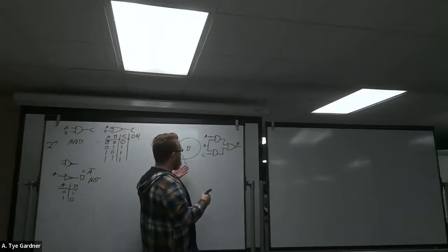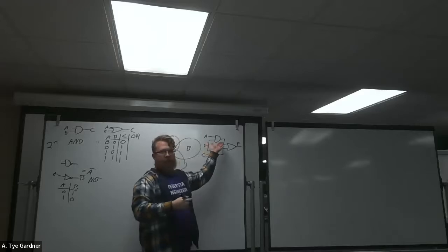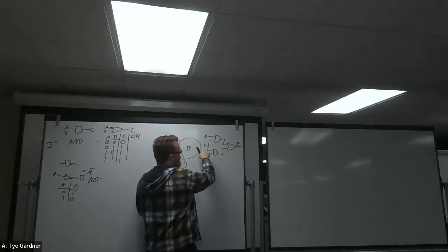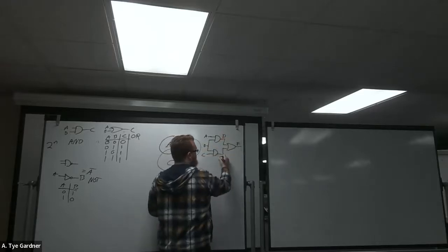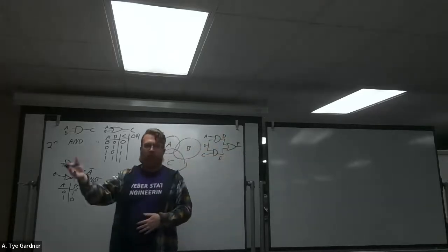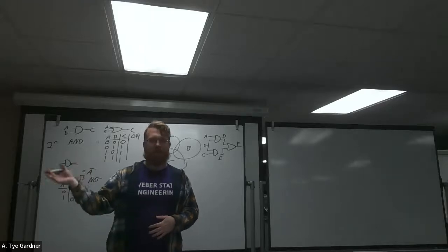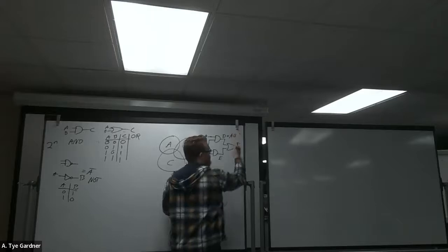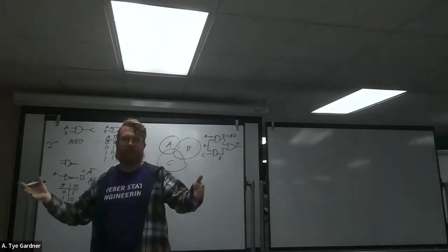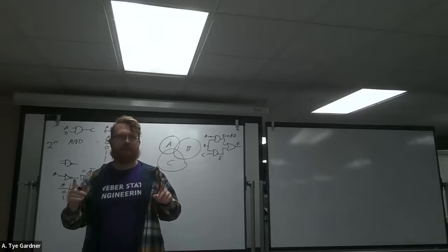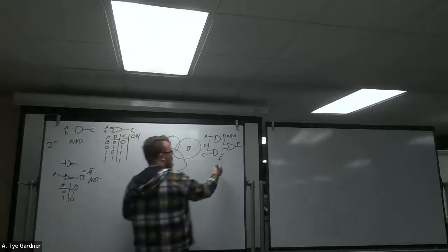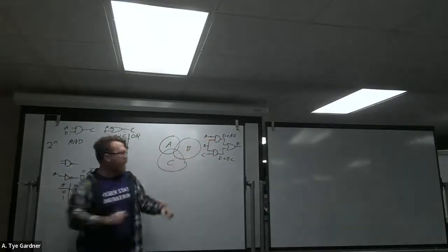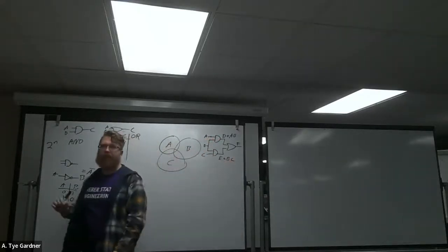These expressions, when I do them, A and B, right? This is an AND gate. I'm going to use an intermediate signal. I'm just going to go ahead and write it out. A, B, C. I'm going to call this D and that E, right? Even if I don't give you these names, you can make up a variable for them to write an intermediate expression that says D is A and B, because in Boolean expressions, multiplication is AND. We talked about this last time, you remember? Similarly, E is equal to B and C. I do not need to put the explicit multiplier dot, right? That's B and C, same thing.